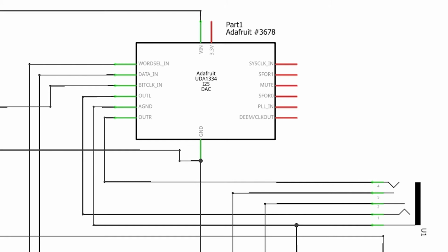Now we want to be able to have both a headphone output and a loudspeaker output for our handheld gaming device. So we'll need this first stage to provide a signal which is suitable for our headphones rather than being a fully amplified signal for a loudspeaker. If we do go all the way to a loudspeaker signal first, then if we try and plug headphones in, we do run the risk of burning them out.